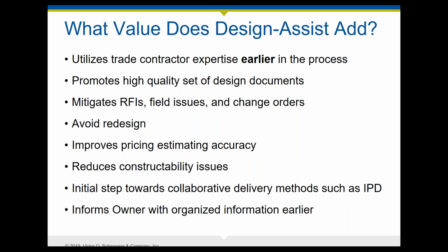In a traditional design-bid-build project, the design team works independently to design various systems, and preliminary cost estimates are prepared as design milestones. The project owner may consult with a CM for pre-construction services to provide cost, sequencing, and constructability information. But then after the design is complete, the construction documents are published and turned over to subcontractors for bidding. The subcontractors are awarded and the process of coordination, shop drawings, and procurement really begins. And then discrepancies may arise and the design team is required to answer questions or provide responses to RFIs. And that often results in project delays, change orders, and added costs to the project.